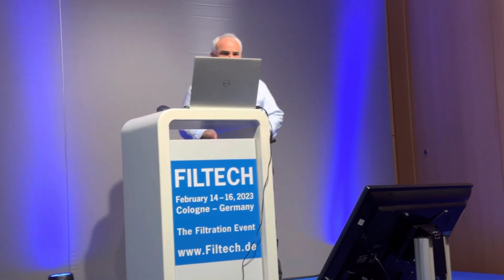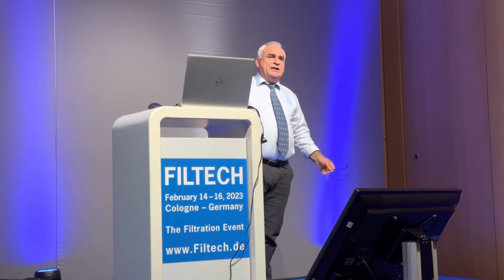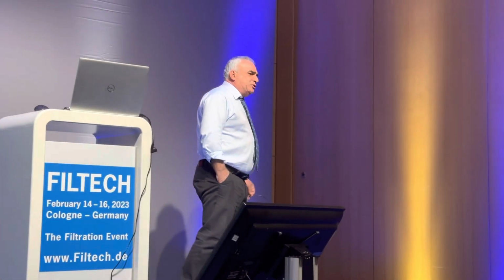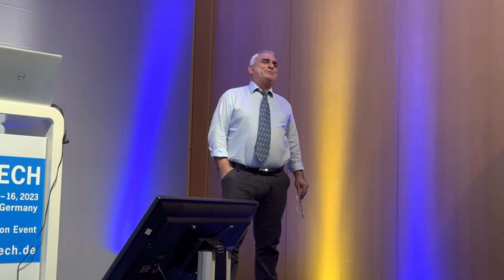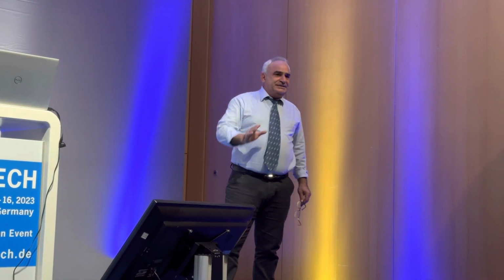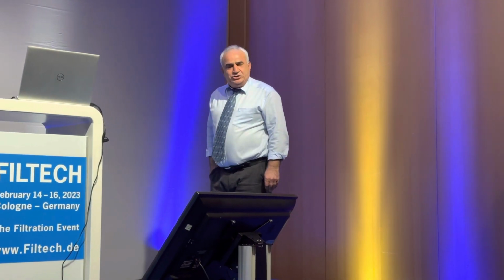For that, of course, we need some tools, yeah? And as we know, when the suspension is not known, not any test data before, then we have to go to the laboratory, for example, a laboratory pressure nutsche, do some tests, and see how the filtration, washing, and delivering behaves.